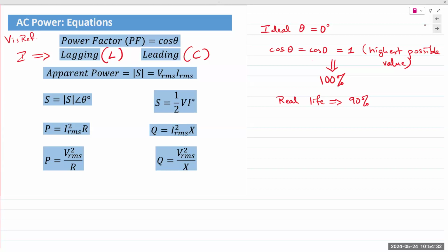If there's a total blackout on campus, campus is huge and requires a huge amount of power. There's a staggered turn on. The power goes out entirely on campus. The central plant and the facilities managers work with the utility company to create a staggered turn on, meaning power comes on one at a time in all the buildings and all the places. If you turn on power all at once, the utility company cannot supply all of that energy. It will say you have to get your power factor up before we send anything to you. Okay, that's what happens in real life.